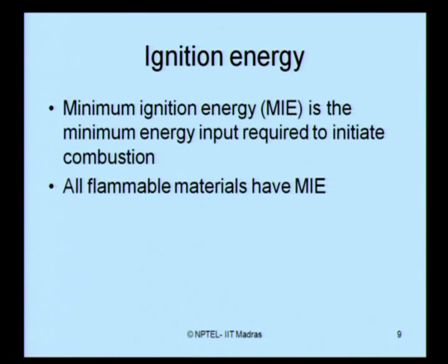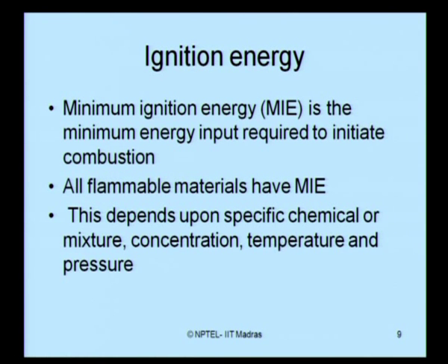Generally, all flammable materials have a minimum ignition energy requirement, and this MIE value depends on the specific chemical or the mixture of chemicals. When it is a mixture, it depends on the concentration of different components of the mixture, and of course on the operating temperature and pressure of the mixture.